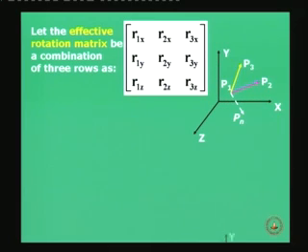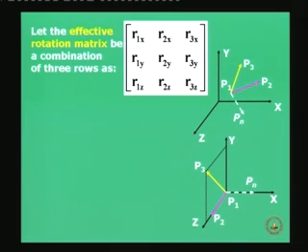And if that is so, what is this rotation matrix supposed to do? The P1, P3, P1, P2, P1, Pn vectors will be transformed in such a manner that P1, P2, the purple color vector, gets aligned with the z axis, the whitish dashed vector P1, Pn aligns with the x axis, and of course, the P3 vector also lies somewhere in the yz plane.